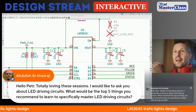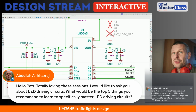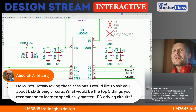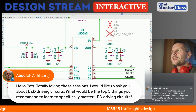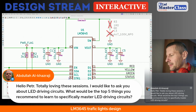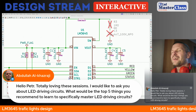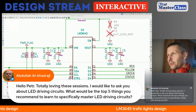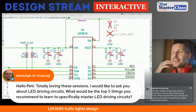For instance, 5 volts can be a typical reverse voltage, or slightly bigger, but you can't expect 60 volts or 100 volts. So when you drive the LED circuits, you have to be careful about reverse voltage, because reverse voltage can damage your LED component easily.